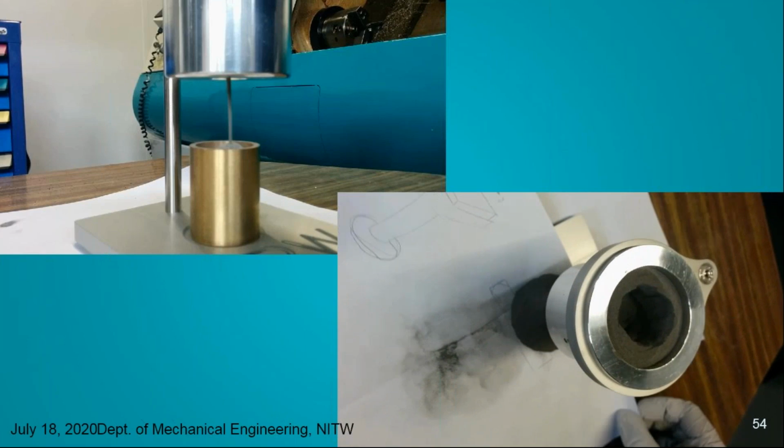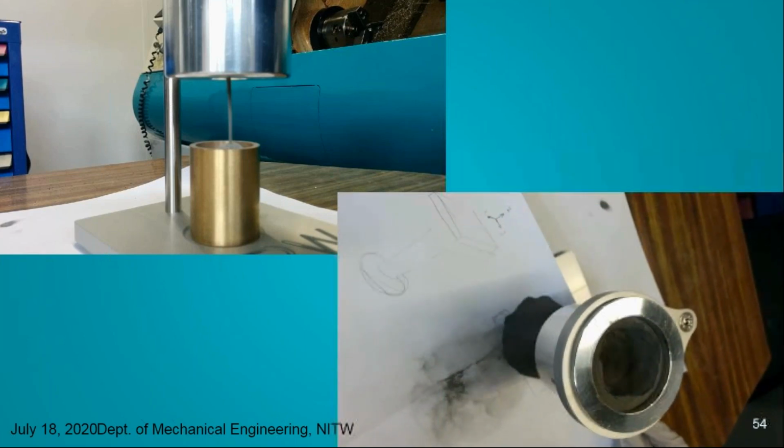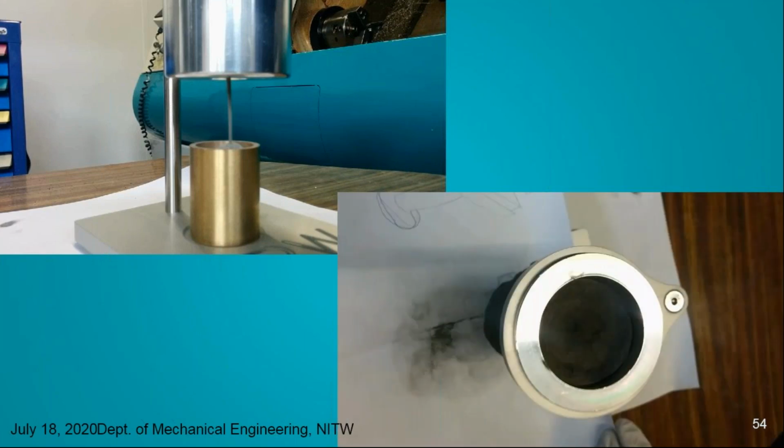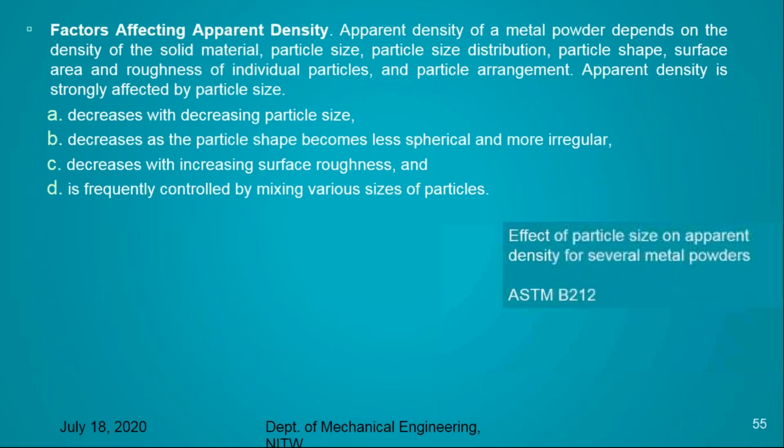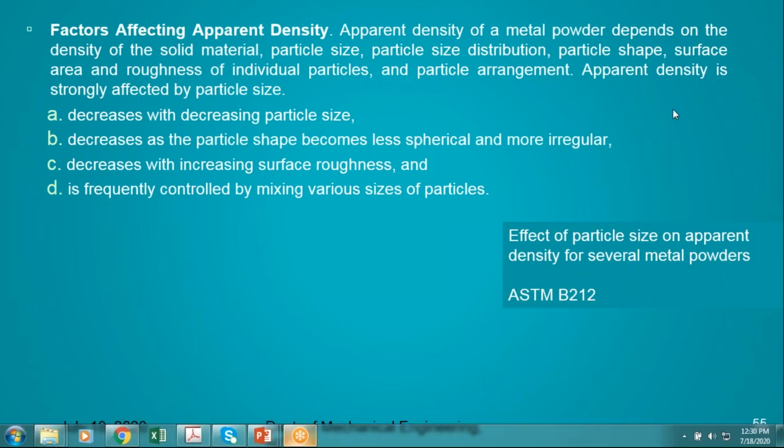It tells us that if the flowability is not good, the powder cannot be suitable for the SLM process or the DED process. We have to improve the powder flowability, and only then can we use it for the additive manufacturing process. Now, some of the factors affecting the apparent density. The apparent density of a metal powder depends upon the density of the solid material, the particle size, the particle size distribution, the particle shape, the surface area and roughness of individual powder particles, and the particle arrangement. That gives us the apparent density of the powder particles.